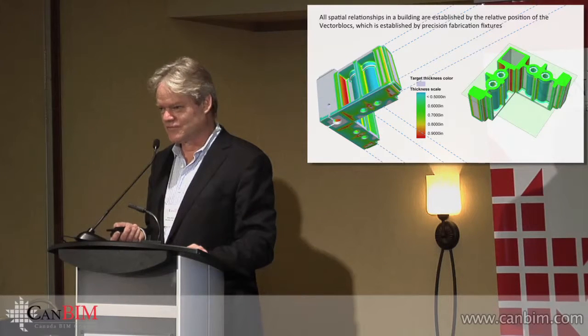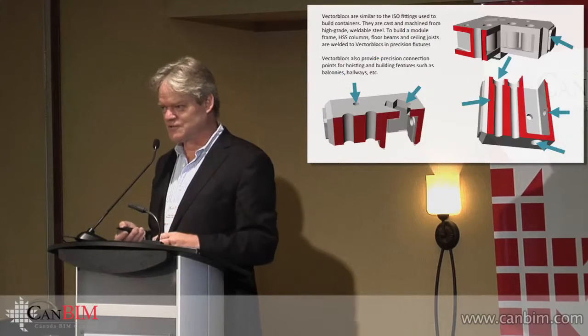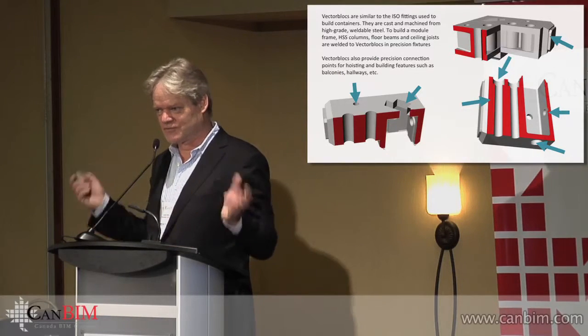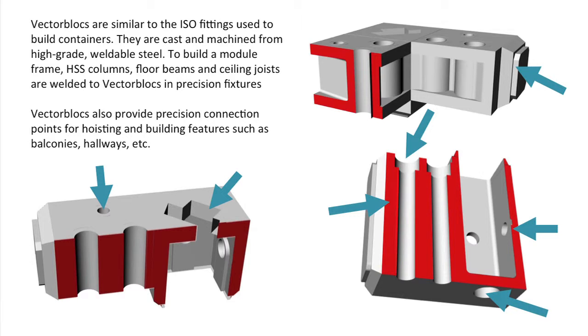There's all kinds of features concentrated in these blocks, so basically anything that would require machining, precision, drilling, threading, anything, all goes in the block, and the members in between them are just dumb members. They can have angle cuts, they can be too short, they can be too long. You don't have to drill any holes in them.